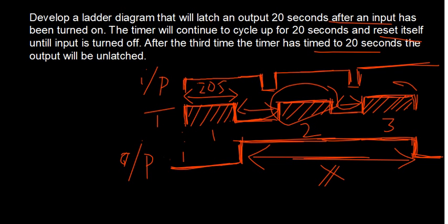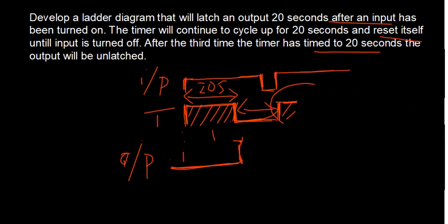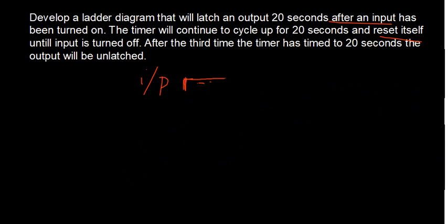My input as usual happens to be the first one, and whenever I use the timer and counter, needless to mention that your timer contact with a normally closed contact would appear in the first rung itself, so that every time the counter increments, the timer resets itself and starts making the required delay again.